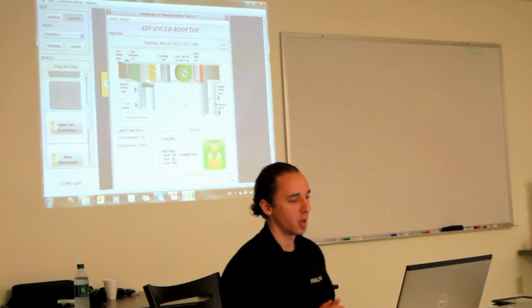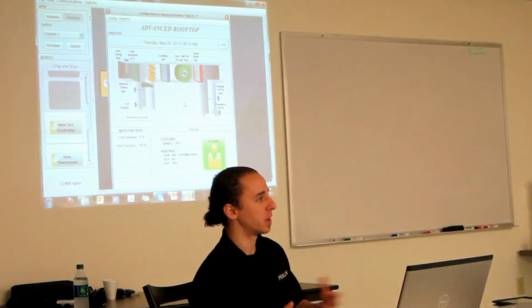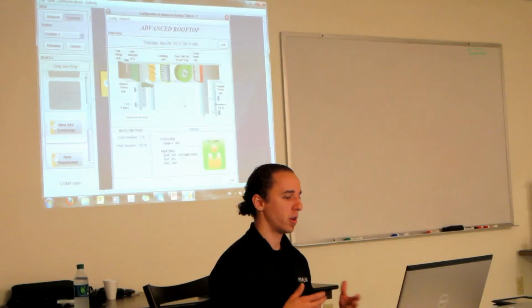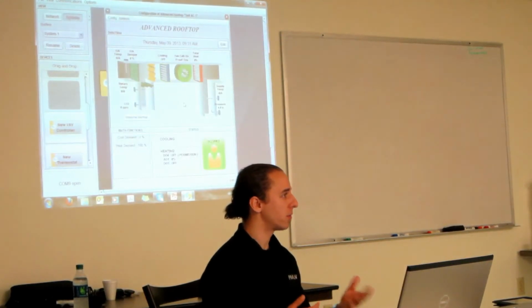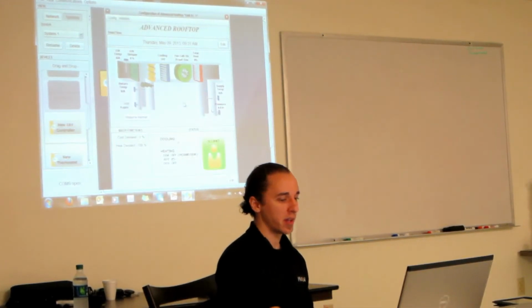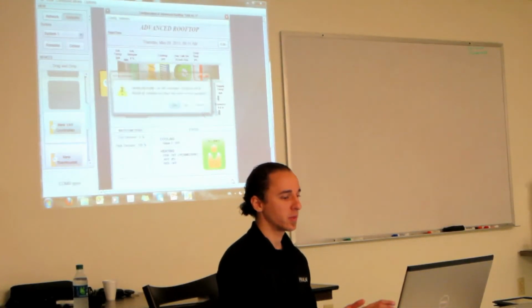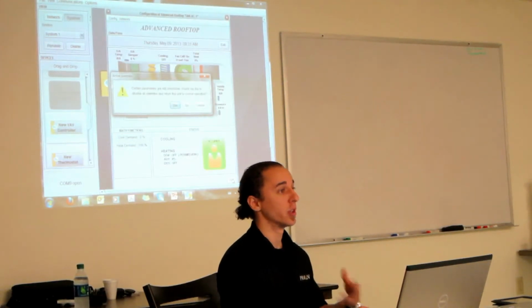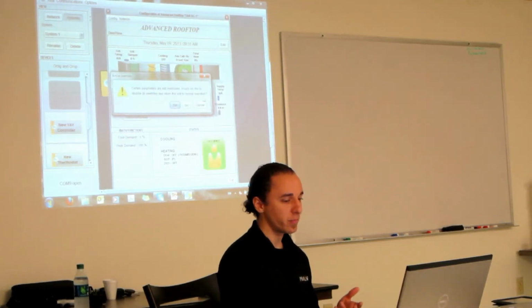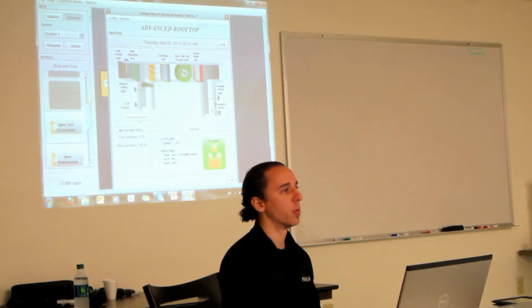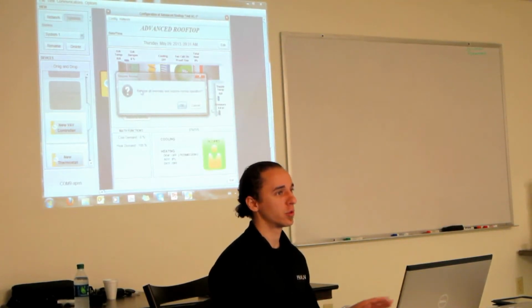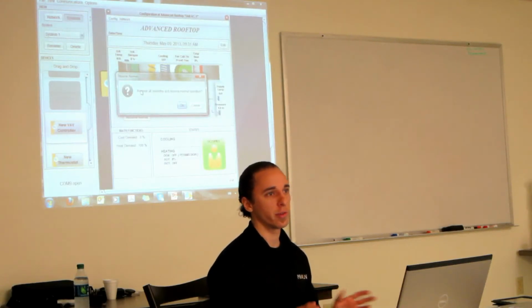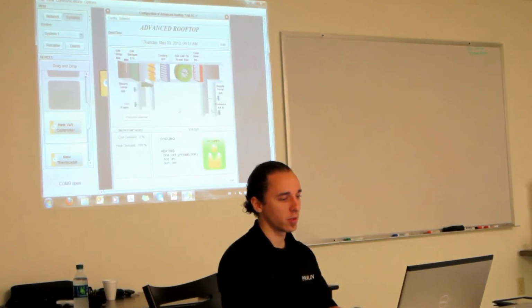It's overridden. Now, supposing you've been working on your system, configuring it, and you've overridden a bunch of things, and then you take most of them off, then you forget that one, and then you press exit. Warning: certain parameters are still overridden. Would you like to continue? Yes, no. There's also a resume normal button as well. If you just do that, this will remove all the overrides. So it's two different ways of taking these overrides off.